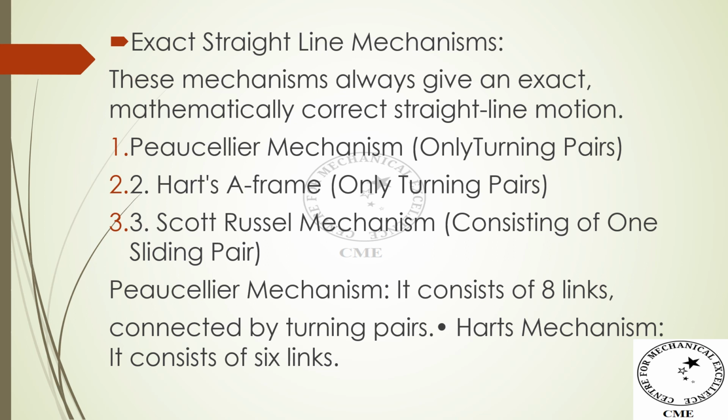The commonly used exact straight line mechanisms are the Peaucellier mechanism, the Hart mechanism or Hart frame mechanism, and the Scott-Russell mechanism. In the Peaucellier mechanism and the Hart mechanism, only turning pairs are there, not sliding pairs.